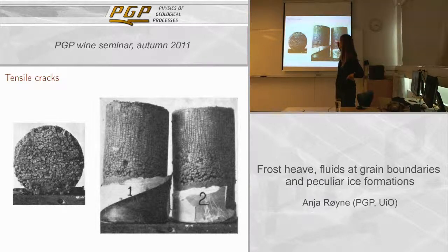Then, as water was being drawn to the top for freezing, it dried out the clay at the bottom, and it created these tensile cracks going in this direction. So from the bottom it looks like this. This is the columnar structure. And then as it kept freezing, you got subdivisions in this direction because of ice lenses forming in each column. So I thought that was pretty cool.